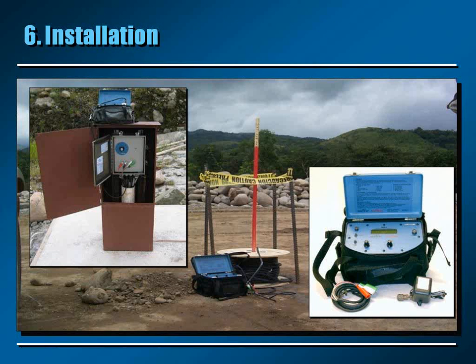Now you can see on this picture a vibrating wire readout box, and it is connected to a switching box to which many piezometers are connected. You can see that there's a rotary switch, and it's possible to select different piezometers and take a reading that way.